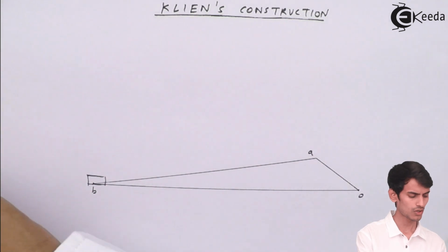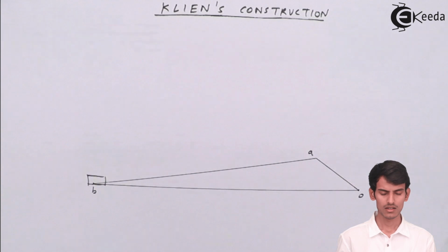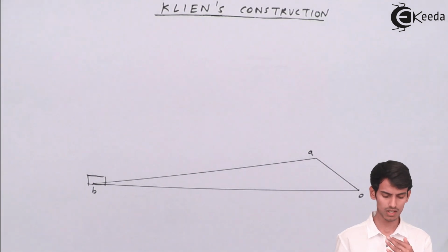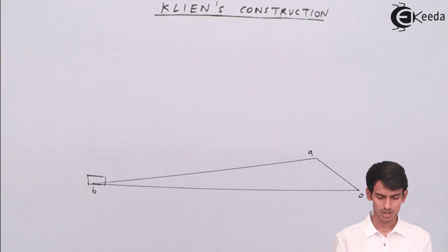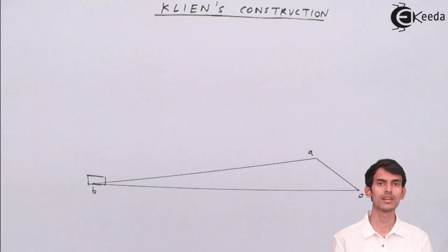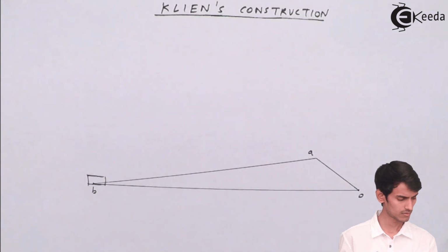So first of all, to get the velocity triangle, you have to extend the connecting rod in the reverse direction, backside, and also from point O you have to draw a perpendicular line to the horizontal. So after these two lines intersect, you get a velocity triangle.